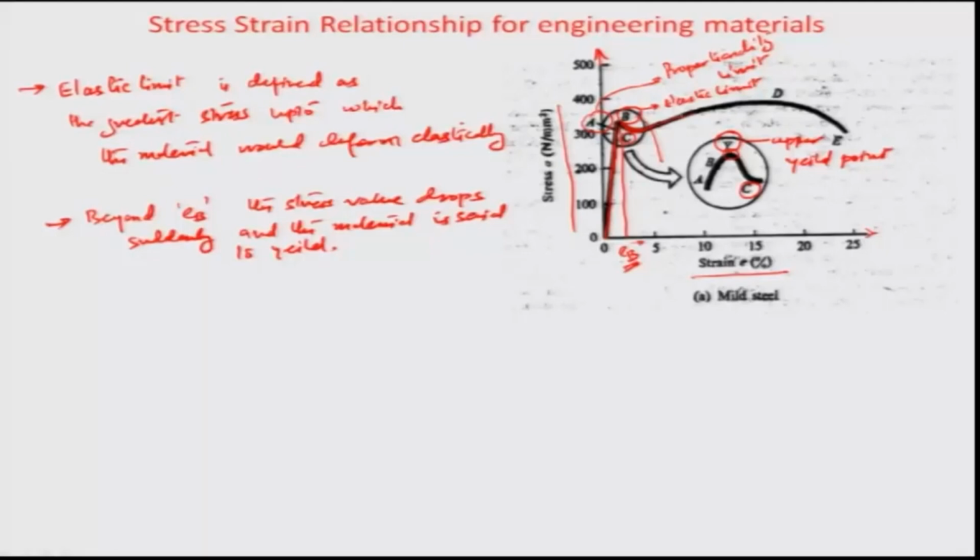So, here in this case also a similar kind of hardening behavior is observed, and the stress again rises, as you can see, all the way to the point D. Okay. So, it goes to this particular point right here. C is basically recorded as the lower yield point, just as Y was the upper yield point, because obviously this is the point beyond which again the stress pattern would change and hardening would start to take place. So, this material is really the strain hardened part.